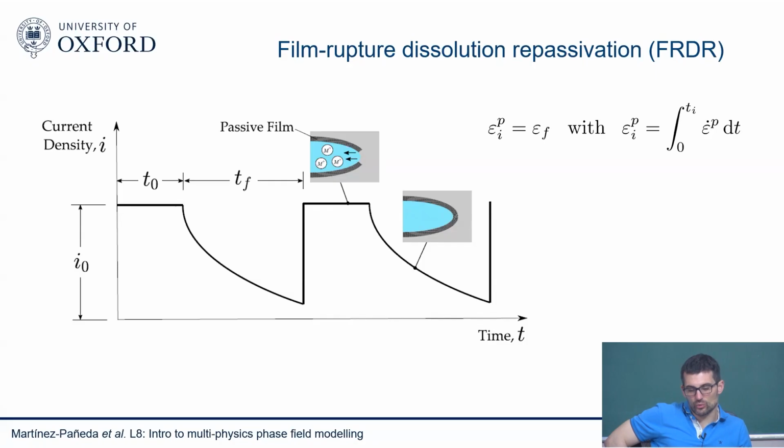But that's an issue to a certain extent, in the sense that if you rupture that passivation layer for whatever reason, you may have some ions that are able to rupture the layer, you often have mechanical fields that are able to rupture the layer, then you get localized corrosion. And localized corrosion is pretty bad because you don't see it, it's very difficult to detect, and it leads to pits, stress concentrators, regions where your electrochemistry is going to change, and that leads to cracks, and so on and so forth. So localized corrosion is a big problem, and responsible for many of the failures that I showed you before.